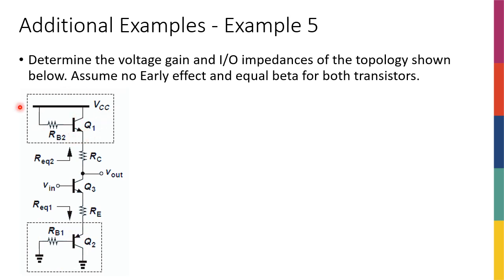Most likely I'm going to see them as resistors because, well, of course, in the DC analysis, it's going to be hell, and good luck with actually analyzing this DC because you have to write a KVL from here to here, and then basically from here down to here probably. Well, yeah, you didn't have to actually write the top one. So you probably write from V in all the way to here to the ground so that you can actually find this current, and then once you have this current, you find this current because they're related, emitter and collector of a transistor. And then once you have this current, it's an emitter of Q1, so you have the collector of Q1, base of Q1, and etc., etc. But that's not the point of this example.